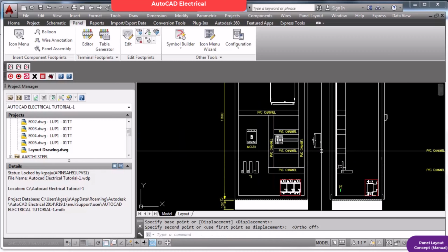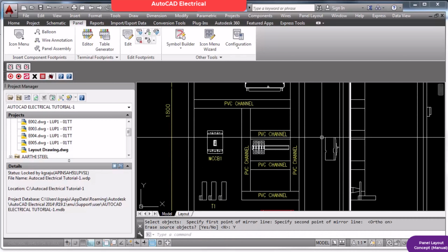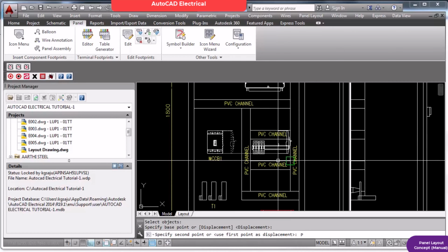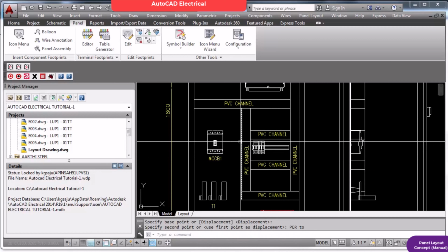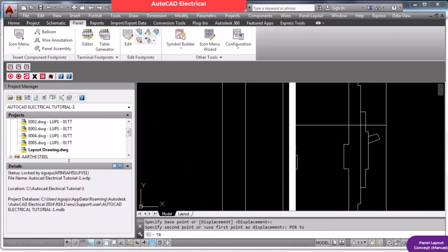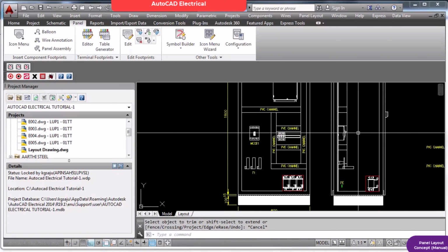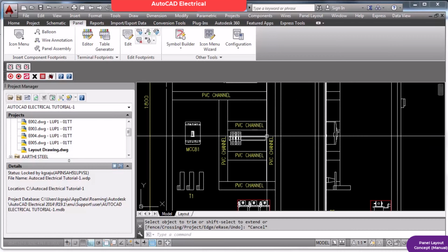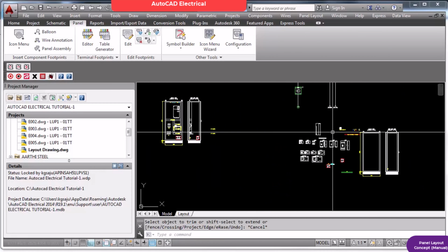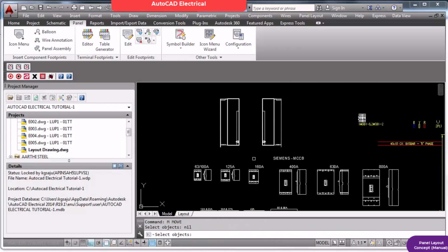Again, next the MCCB. I have a side view of this MCCB. This is the side view. You should always maintain a library. That is the way you can speed up. From the left, when I view this, it should be in this way. See. I'm going to mount it here. Again, when you look from the left, this duct won't be visible. You will only see the MCCB, so I'm going to trim. These are minor things. This is not going to affect your panel at all. But as a good designer, you should practice such things. Front view, side view, everything should be very clear.